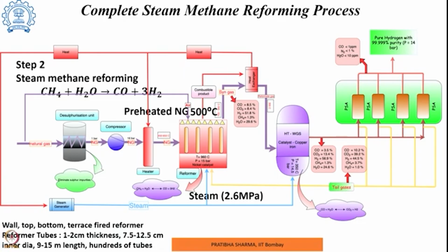Now, these reformers are tubular box-type furnaces. Depending on where the burners are located, they can be either top fired reformers, bottom fired reformers, side fired reformers if the burners are on the side, or terrace fired reformers.